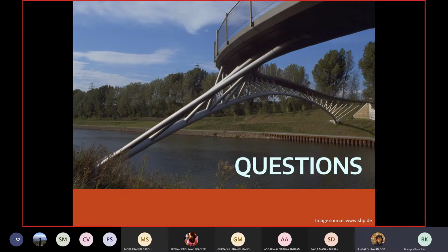So if a grillage foundation is encased in concrete, why are we worried about the water permeability, since it's already acting like a concrete member in terms of water management? We can always protect it from water that way. Yeah. So in a sense, even RCC bases are just steel encased in concrete, right? The reinforcement is as prone to water damage and corrosion as the steel base in a grillage foundation. That is correct.